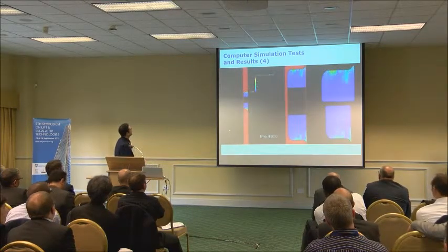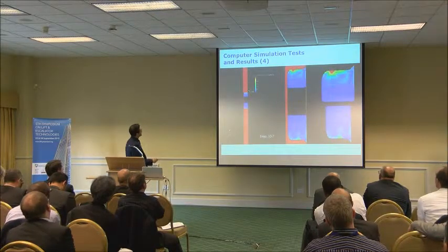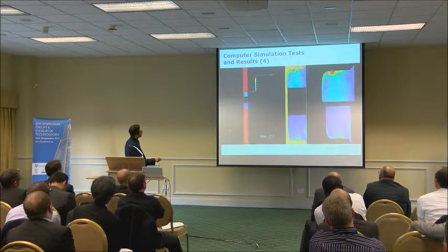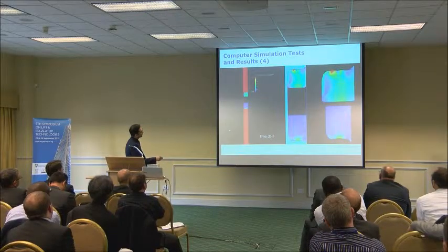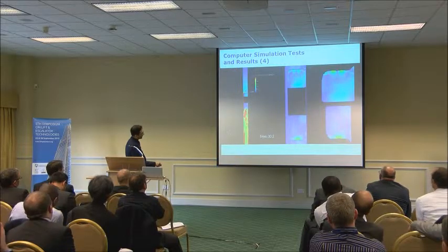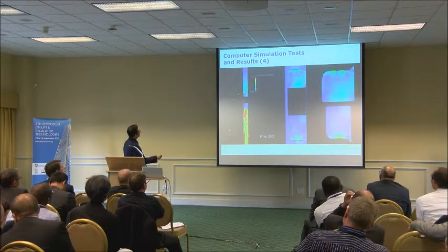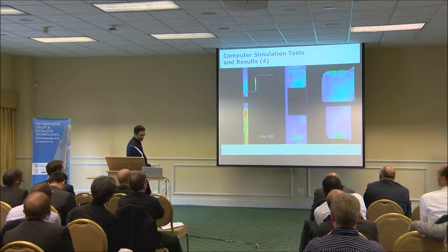This is one of the simulations we have for the car, showing the velocity around the shroud itself. Inside the shroud we see there is an exit point for the cable position, so the air can go inside and will be trapped in here. We also have the exiting cable position, where again the air can travel inside, and you can see it in the bigger picture on the side too. The whole thing starts with laminar flow at the beginning and ends up turbulent at the end.